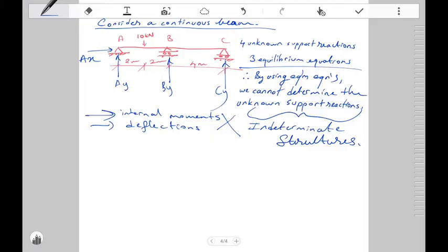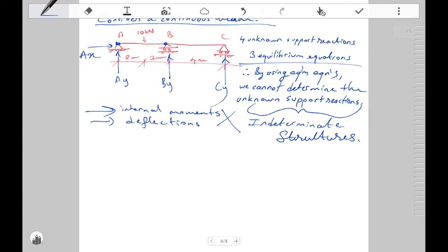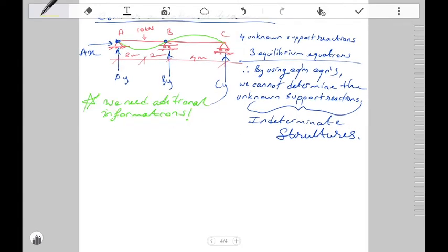I'll take a look at the deflections or the deformations. What additional information do I have? I have a pin support at A, right? Here the deflection is equal to 0 in the X and Y direction. Likewise, at B, deflection is 0 again.